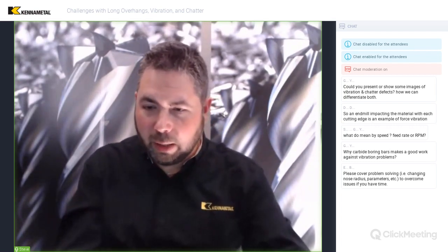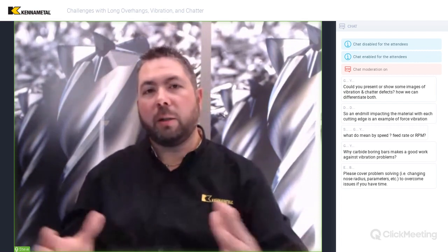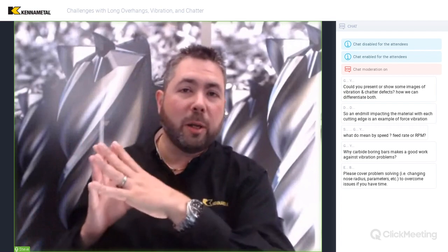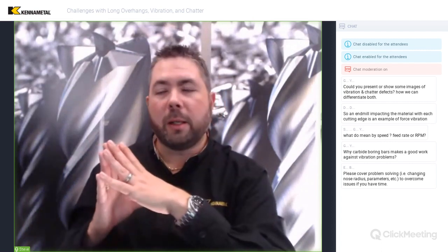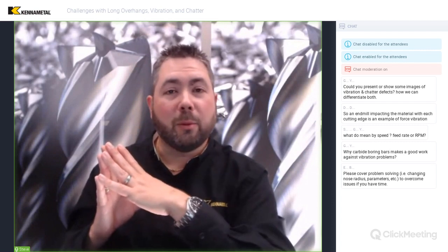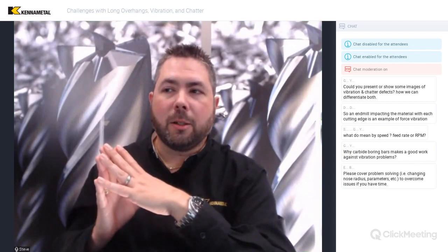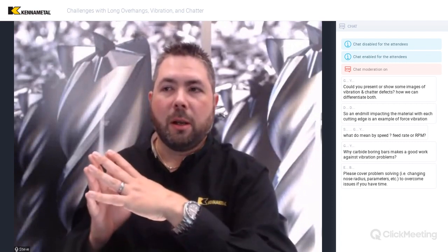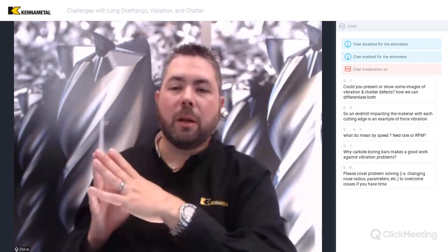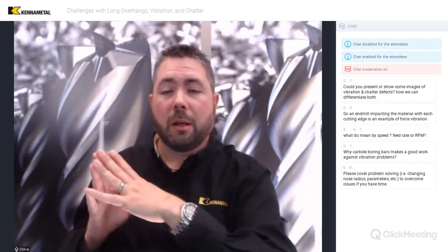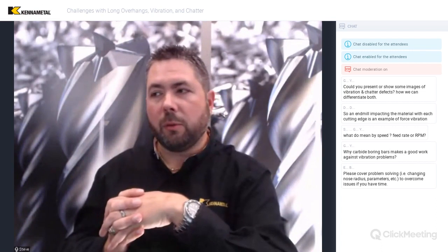Let me just check and see if we had any other questions come in. I don't see any. So let's just recap. We talked a little bit about what vibration is, and we talked about it being oscillations. We talked about chatter coming from that. Obviously we don't want it, but why does it come into play? Probably just another thing to mention, we've talked in some of our other webinars about stiffness in terms of deflection. This all comes into play because we're talking about essentially the spring element side of all of this, and how much deflection we have relative to force. So keep that in mind in terms of your overhangs.